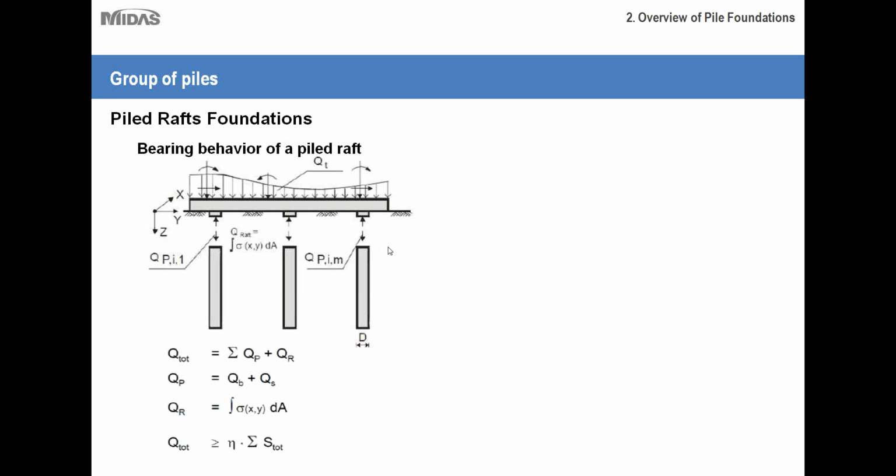The behavior of a pile raft foundation is very complex, and it's more complex than single or group pile behaviors. With pile raft foundations, you can do away with a PY curve approach, several iterations for a single pile. But for pile rafts, it's very important to use numerical analysis programs like GTS NX. 3D analysis is pretty much necessary for these types of foundations.